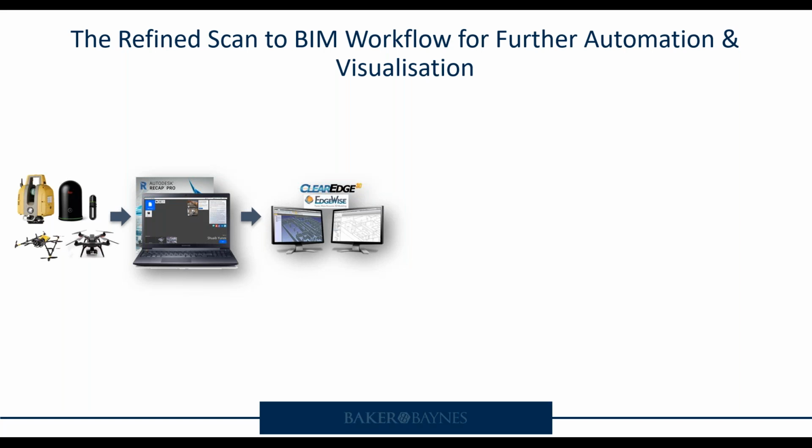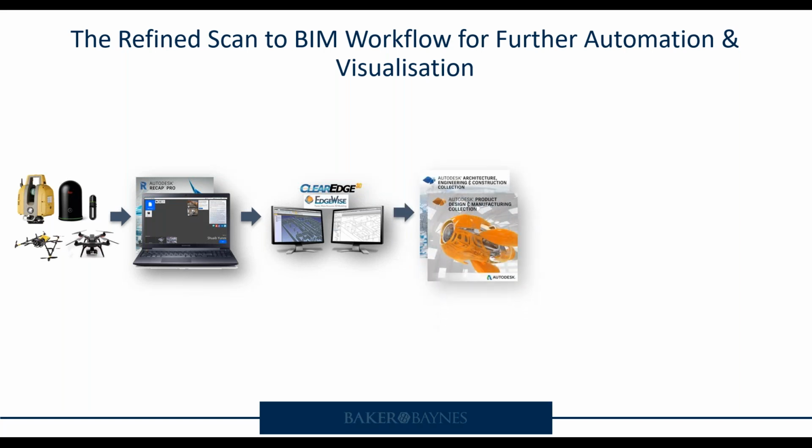But if you haven't heard of it, there are point cloud geometry extraction technologies. It's a bit of a mouthful, but what it does is it identifies the linear objects like walls and stuff like that in your building, and it extracts the geometry for you. So it saves you like 70 to 75% in the modeling phase, which is amazing. And once you do that, you could incorporate that into Revit, which is the flagship software used in the built environment. And it comes in as Revit Intelligent Family.